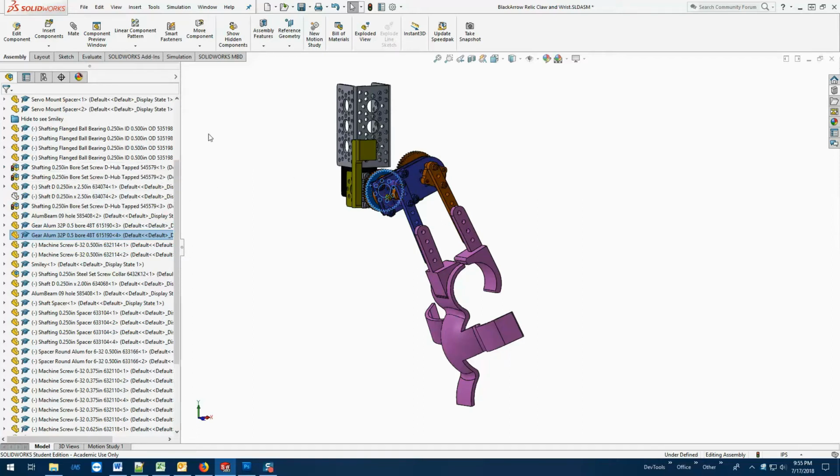And if you'll notice, that exactly matches this menu option up here. What SolidWorks is trying to tell me is that I'm not sure everything is still exactly the way it's supposed to be. Next time you get a chance, press rebuild. So that's what I'm going to do, is rebuild, and you'll notice those things went away.